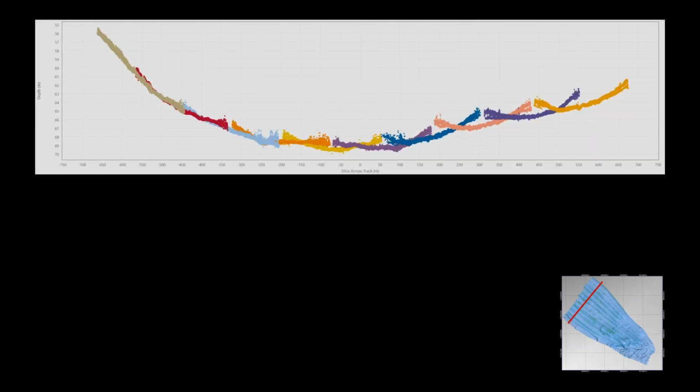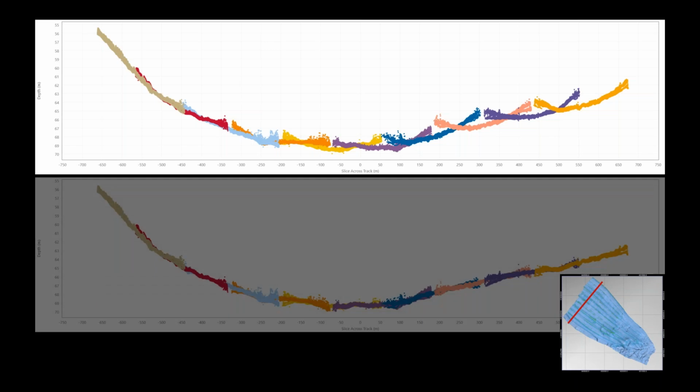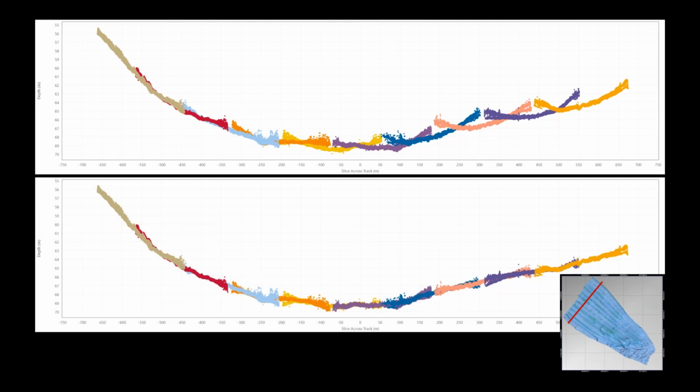So let's talk a little bit about the results. I grabbed a slice of data. On the lower right-hand side, you'll see the overview map with a red line showing a section, and that's the initial set of points that we demoed in that first video. And that's basically at the top is the before. And after TU Delft running, we get the after. And you see there's really, really nice agreement, as much as we possibly can, between the successive passes and the different survey lines.